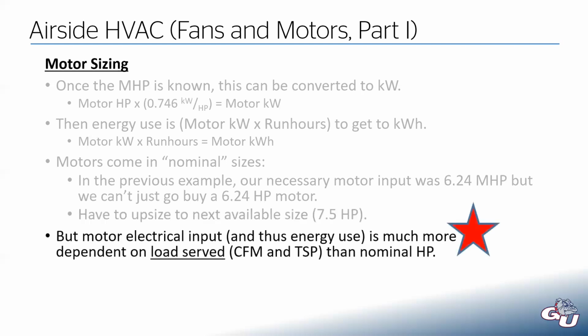But keep in mind, the motor electrical input, which also equates to energy use, is so much more dependent on the load that it's serving. So that CFM and the total static pressure, that is what is going to drive the energy use of that motor much more than the nominal horsepower.